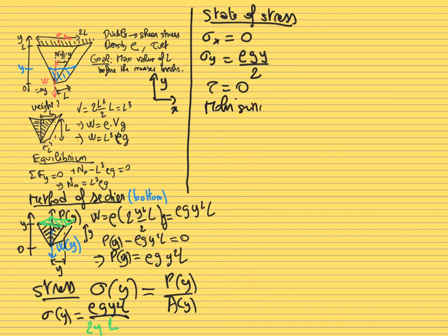Okay, so we are going to now draw the Mohr circle. For this, the different steps. First, we just calculated the state of stress, which is always the first thing that you need to do for a Mohr circle. Then we are going to start by putting the axes of the Mohr circle. As a reminder, the x-axis gives you the stress along the x-axis.